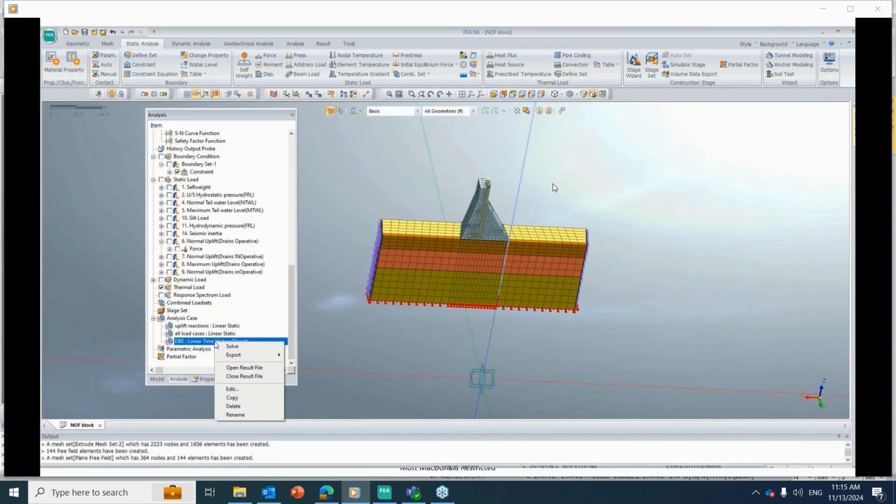In a dam, it is 1.5 times the seismic coefficient at the top, and this dam is founded on sound rock, which vibrates in phase with the dam. I mean, the material of rock and the concrete is almost similar. So that alpha h variation, the seismic coefficient variation, is 1.5 alpha h at the top and 0 at the bottom for a dam. For a building it is different, because a building is a portal frame structure. So it is different for that.